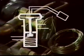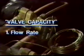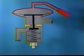One of the primary purposes of a TEV is to meter refrigerant to an evaporator coil. Since all flow must pass through the valve, the flow characteristics of the valve is critical. It is this flow that determines the valve's capacity. The measure of a valve's capacity depends on two things: the quantity of liquid a valve can physically pass and the operating characteristics of the refrigerant itself. The actual size of a TEV is only a part of its ability to pass enough refrigerant to allow the evaporator to do its job.